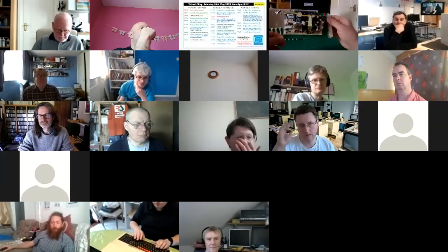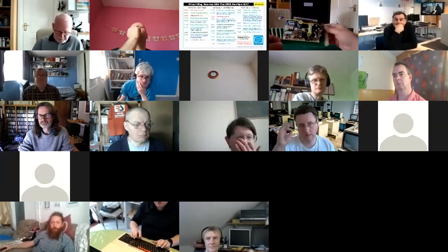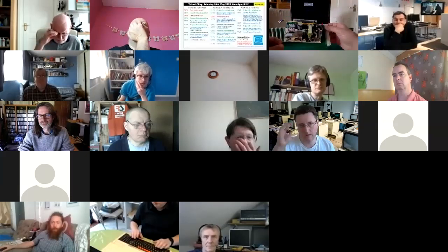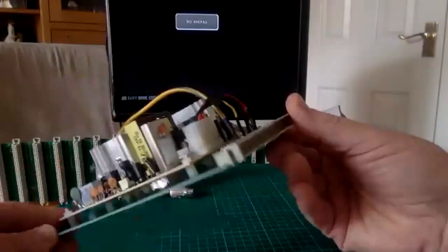So the power supply is basically one of these, I think it's PT65, isn't it, that you'd find as a replacement for a Master or a B, but there's kits available for that. I'm putting 5 and 12 volts into the backplane on that. So that's one of the boards I had built up from PCB way that I knocked together quite quickly.